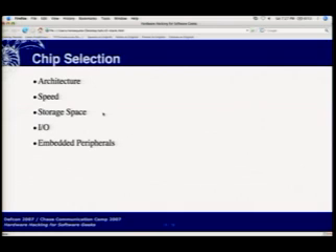A lot of microcontrollers have moved to system-on-a-chip architectures, where you've got not only the CPU core, which is the core that determines what instruction set it uses, but also standard peripheral systems. So you're going to have like an SPI module, maybe a couple CAN modules, which is a proprietary communication protocol, which is very common in automotive, marine, and avionic applications. You've got SPI, of course, which is another standard interconnect for other devices, which may be Ethernet chips or whatever. And then you've got EEPROM that might be off-board as well, off-board RAM that you've got to interact with.